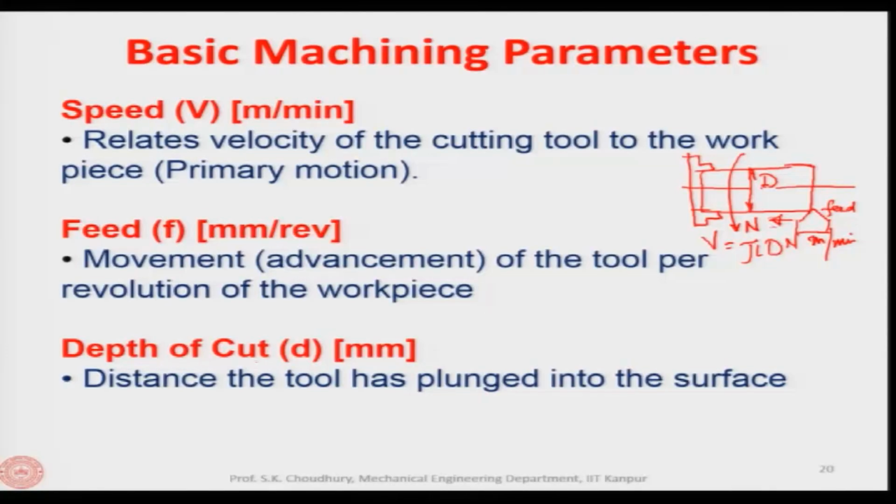Next is the depth of cut. This is the distance the tool has plunged into the surface. For example, in this case, this was the original diameter and the tool is cutting, removing this much material. So, this is the value of the depth of cut.